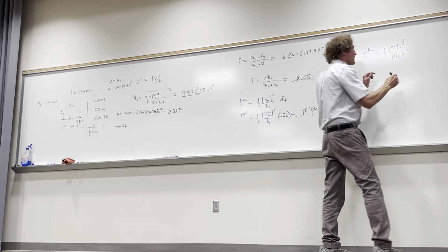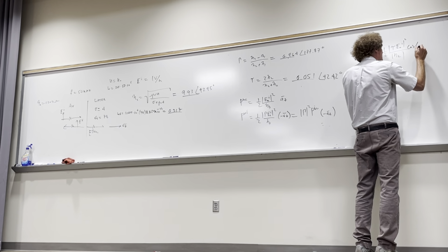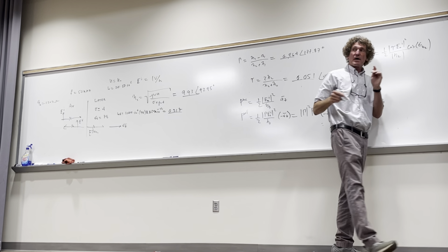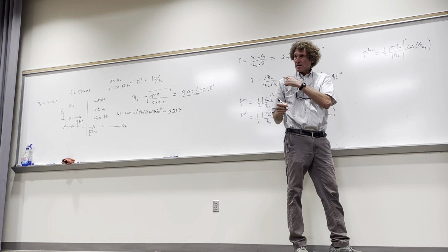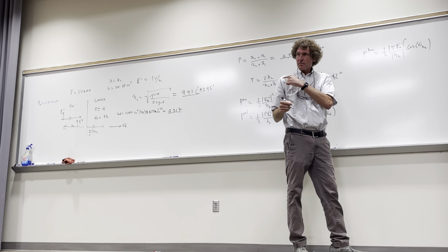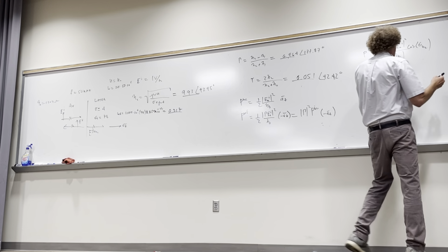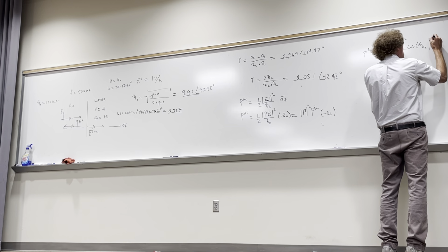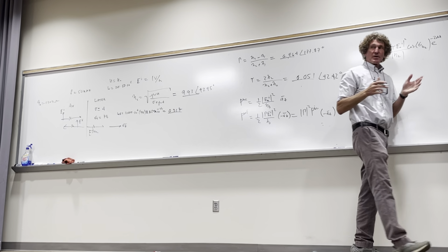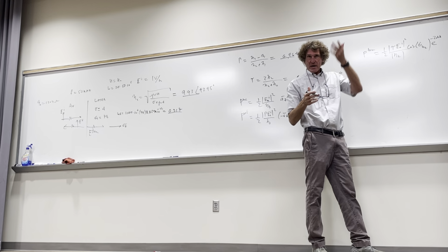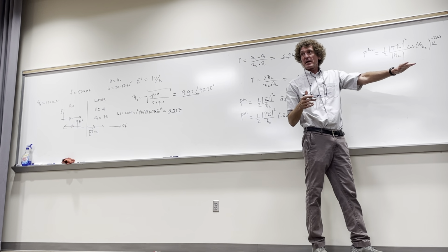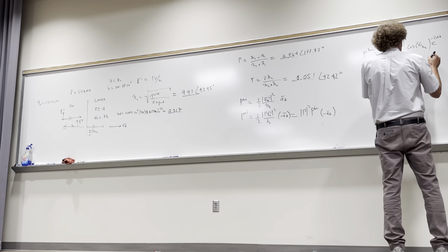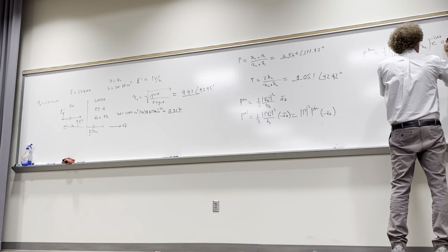Then you have to put the cosine of the angle associated with eta 2, which is almost 45 degrees. Take a look at that. Y'all with me on that for eta 2? And then this is going to also technically have an e to the minus 2 alpha z component if we wanted to be correct as far as its variation versus depth. But we don't have to put that if it's just the ratio of the amount going in. And this would be in the a_z direction.